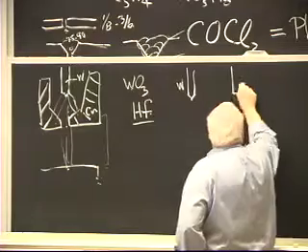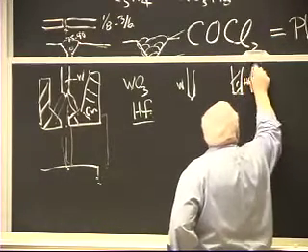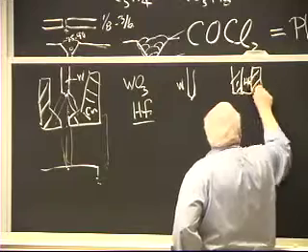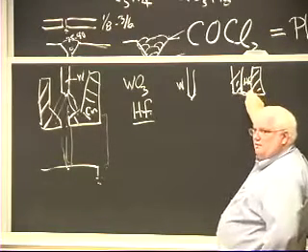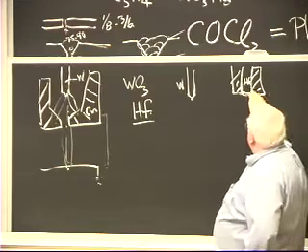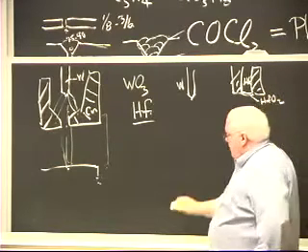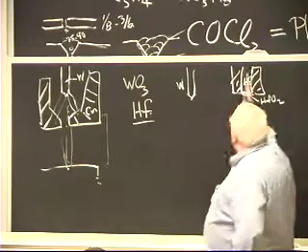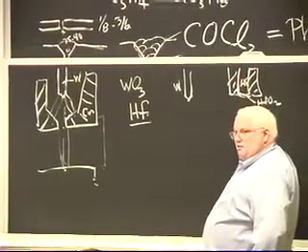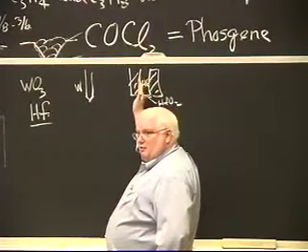They actually embed it in copper, put the hafnium inside the copper, and this surface tip is where you get your current. But this forms a simple little layer of hafnium oxide, and hafnium oxide in a thin layer will conduct electricity. And so you can actually get your electric current through here without vaporizing your electrode. You use a hafnium electrode.